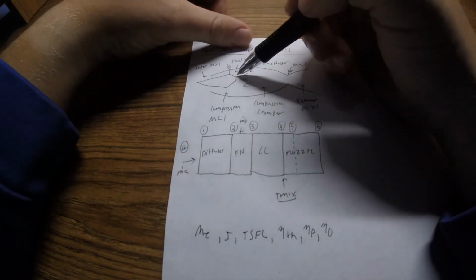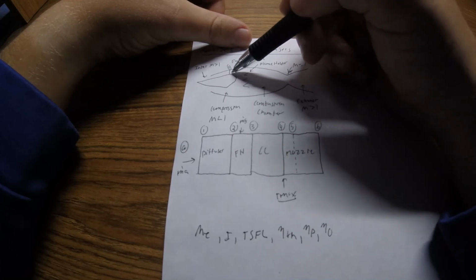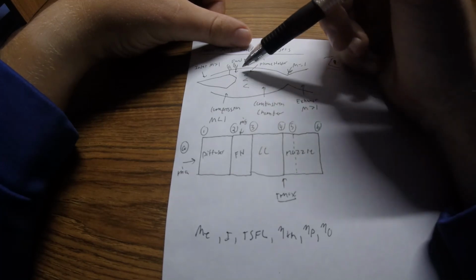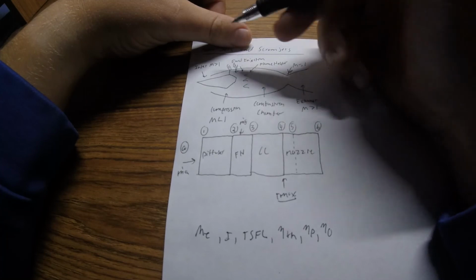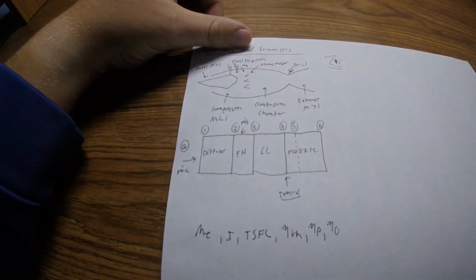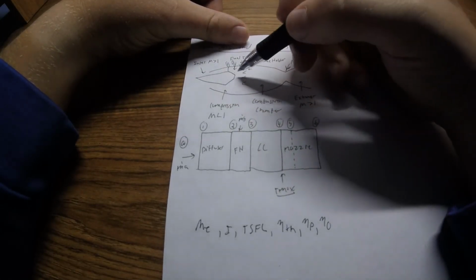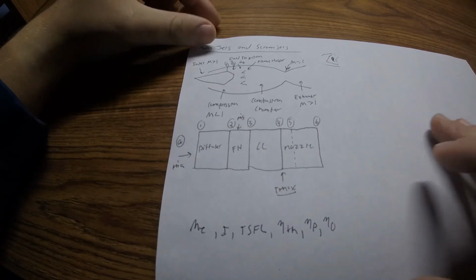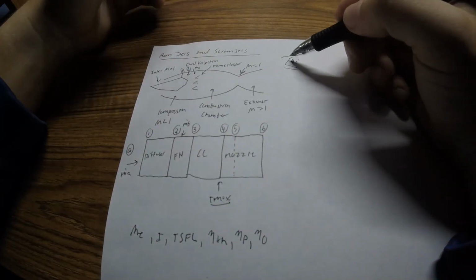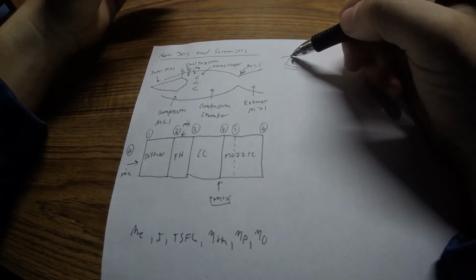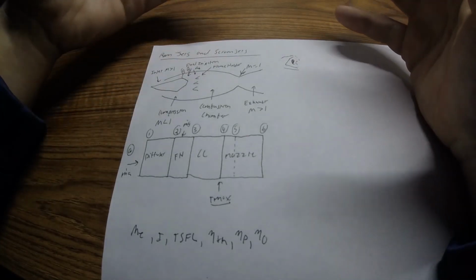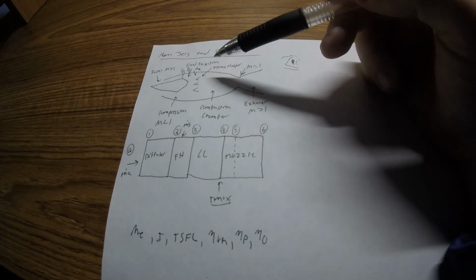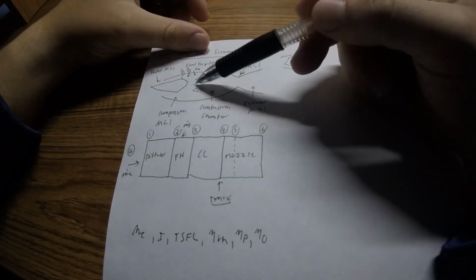Then we have a diffuser here where it releases the pressure a little bit, and this would be state 2. After the diffuser section, this is where fuel injection mixes fuel with the air, and then it meets the flame holder, which is basically where the flame is in the engine. The way the flame holder works is that the flame or spark lighting the fuel-air mixture is behind a wall, therefore creating an eddy, which mixes the fuel in the air more and gets a better lighting action. Because if the flame was just sitting out in the middle here, the air and fuel are moving so fast it might not light properly. You have the flame holder.